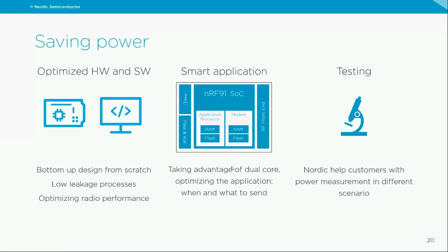There's no need for the modem here to wake up the application processor in advance to tell it that data is coming, such as you typically do with an external application processor and a standard modem. The modem here can simply wake the application processor as data is coming, and the application processor wakes up very fast to receive those data and start any processing.